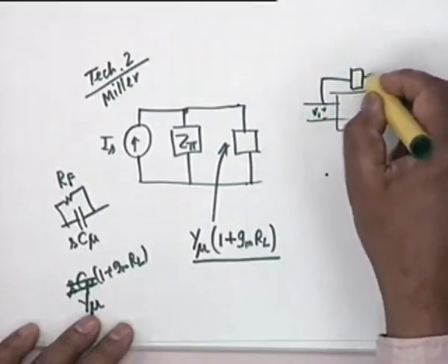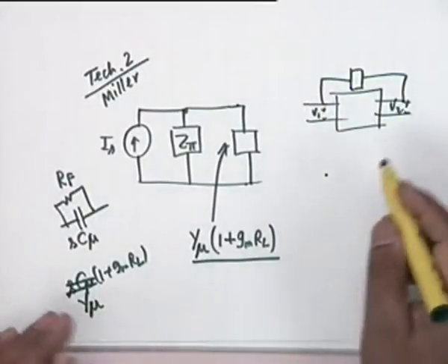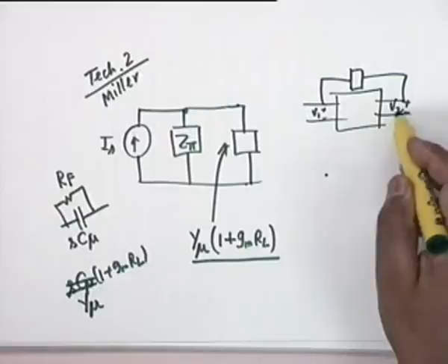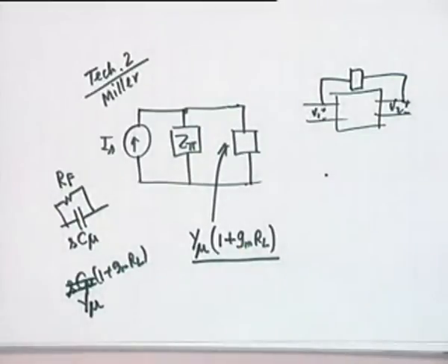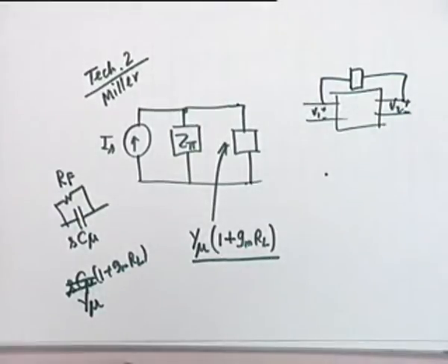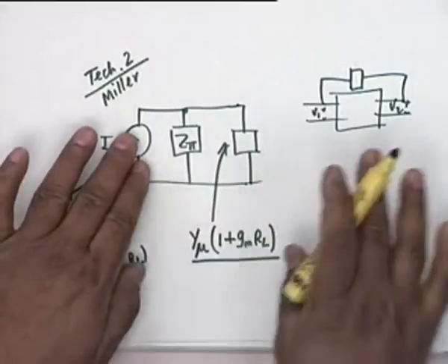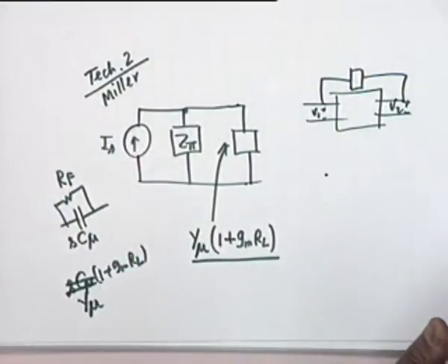Then any impedance that is connected here can be reflected to the input through V2 by V1 and to the output through again V2 by V1. So this current source or voltage output, they have no place. There is a bridging impedance which you don't want to take into analysis, and therefore you reflect it to the input, reflect it to the output. That's it.